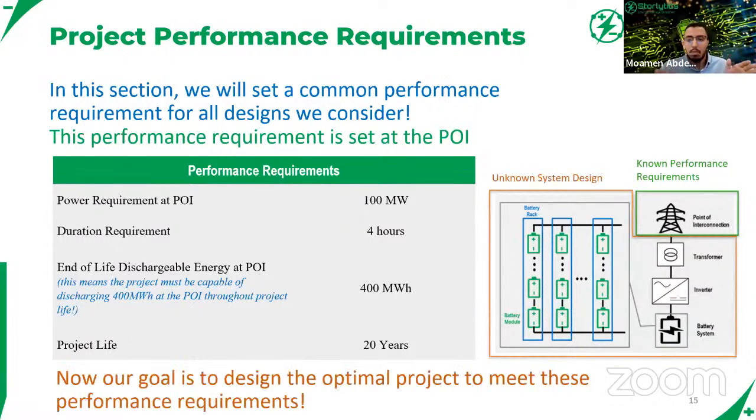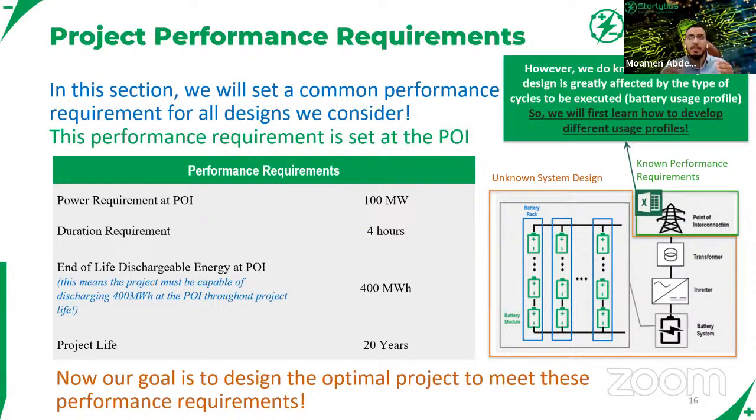Now that you know your performance requirements, what is missing is to start designing your system to meet them. A very important input must be added as a designer, which is the battery usage profile, which simulates the operational characteristics of how your battery will behave at the point of interconnection when you connect your energy storage system with the grid.